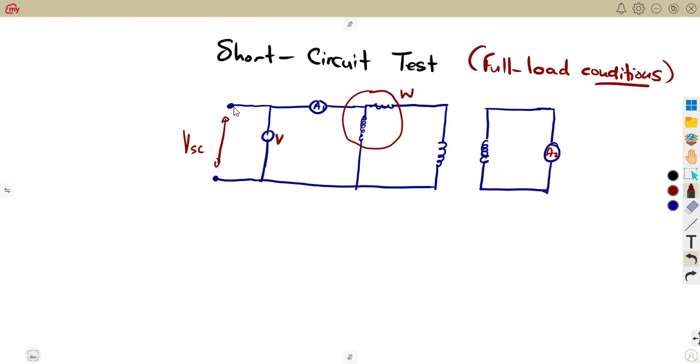So we are saying this short circuit test can be conducted by a short circuit on the secondary side and placing the instruments on the primary side, meaning we can have our V short circuit on the primary side. A voltmeter is given, also the ammeter and the wattmeter. These are connected to the primary winding. You're having this on the primary side, while the secondary side is short-circuited using a suitable ammeter. That's why we have our A2, our suitable ammeter that is given there.